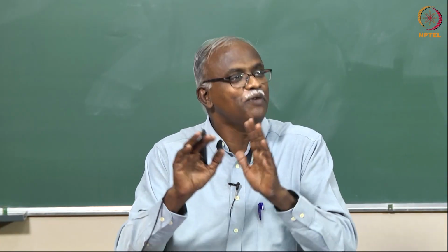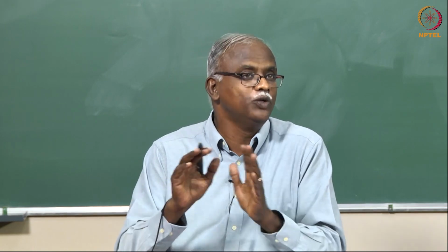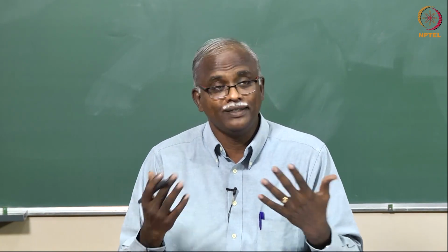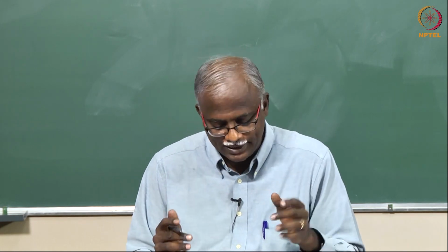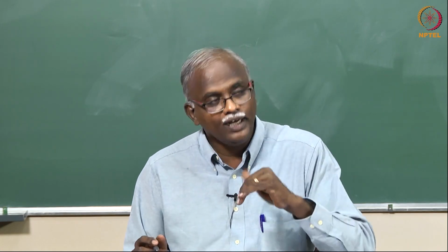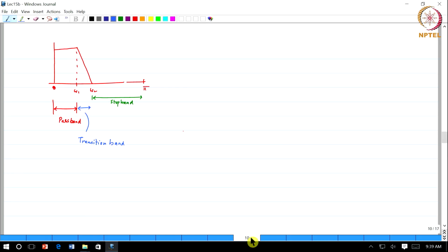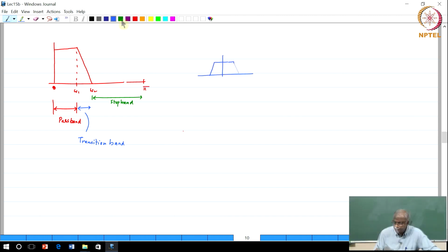Basically you do not really worry too much about it, but you want to, because in multi-rate, if you are doing downsampling, then you want to be sure that this will not cause you aliasing, but it is one of those things where that is not where the signal of interest lies. So, this is typically what happens: you have filters that will overlap in the transition band. This is the common framework.